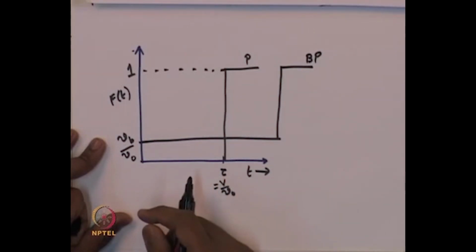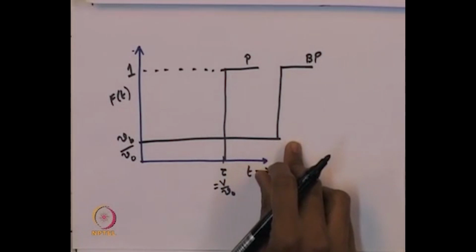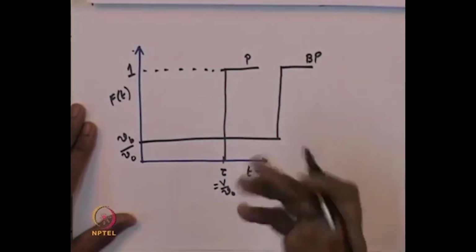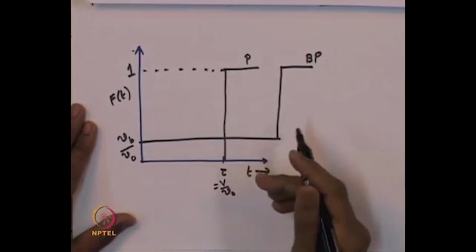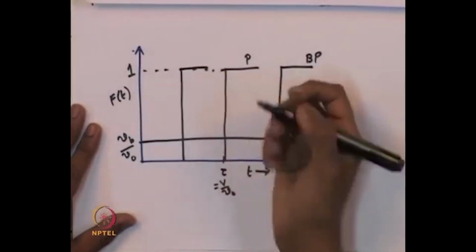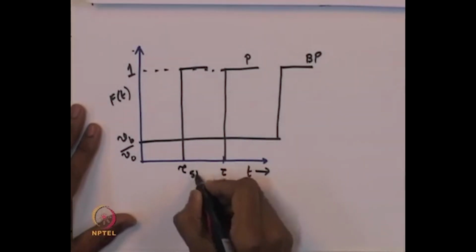And then if there is a dead volume present here, then the net active volume available for the fluid stream to access is smaller than the actual volume of the reactor. Therefore, the apparent space time of the reactor is going to be smaller than the space time of the plug flow reactor operated at perfect conditions. So, the fluid stream will leave faster than in the normal or perfect operation of the reactor. So, this is tau St.